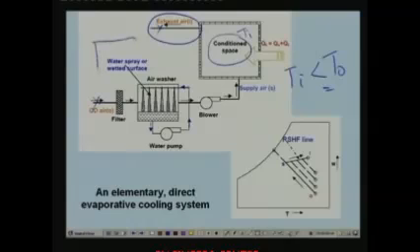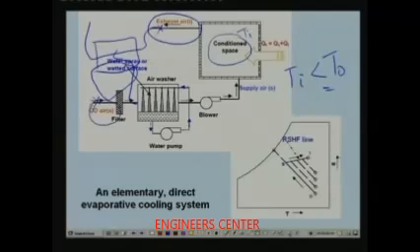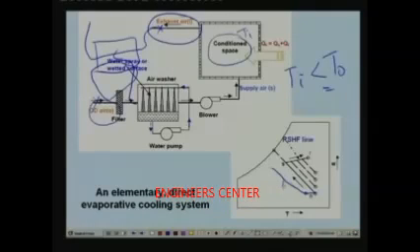For example, if I put a heat exchanger here, okay, so this air flows through this like this, and this primary air before sending it to the air washer flows through this, let us say it flows like this. So, as a result what happens, the temperature of the outdoor air gets reduced as it exchanges heat with the exhaust air. So, what enters the evaporative cooler is a cooled air. That means instead of entering at this point, this will be sensibly cooled by exchanging heat, and at this point cooling and dehumidification takes place. So, you can see that you can achieve lower temperatures by using this simple modification.